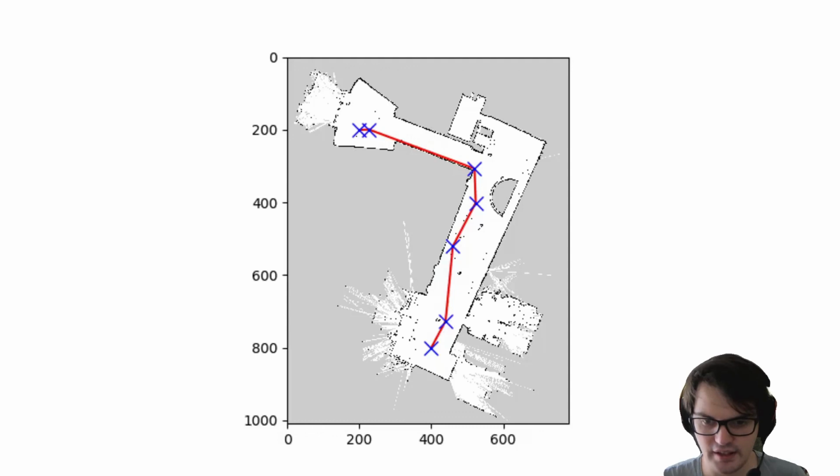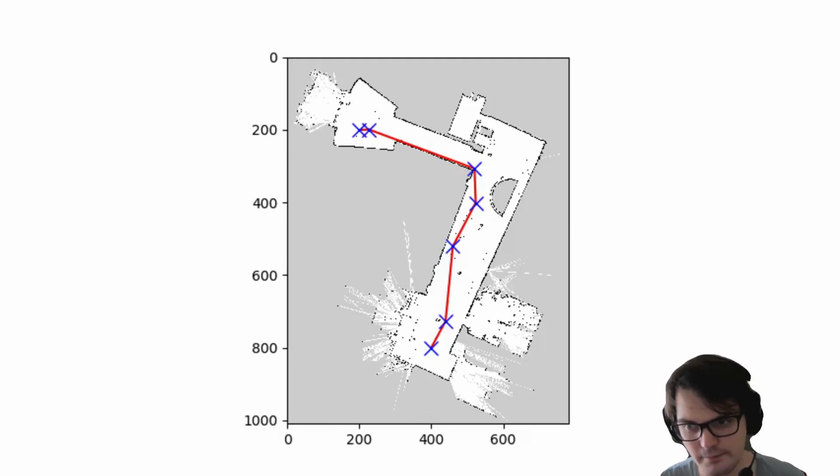We can see here another rather large problem, as we initially did not consider the robot size in our cost function. So when we have a look here, we want to minimize the path lengths. So the algorithm optimized here to drive as close as possible to the wall without colliding.